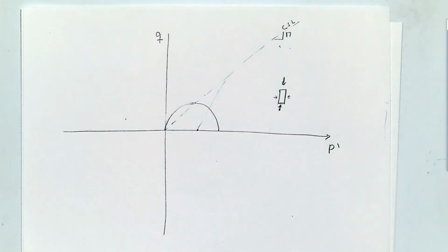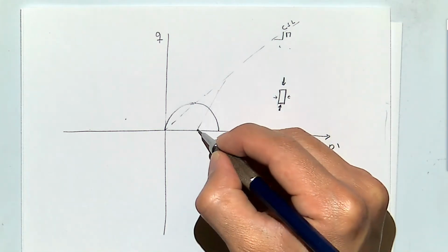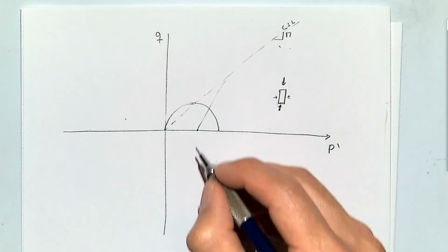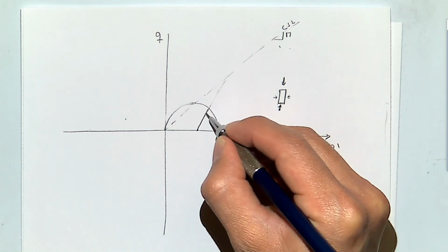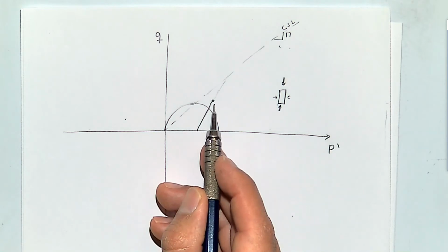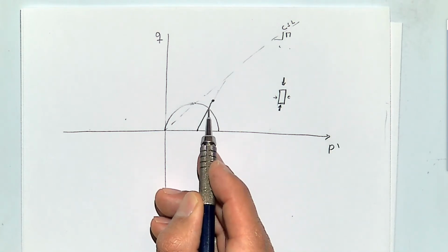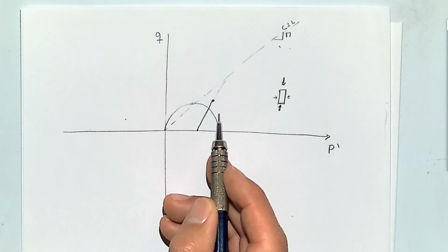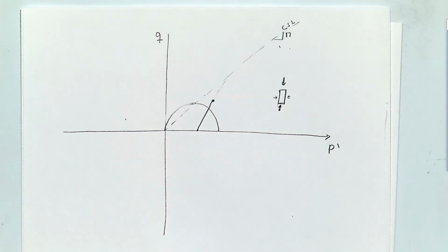The result of this triaxial compression is that when you go over this yield line, and let's say somewhere you stop over there, you have compacted the material and you have gone through a plastic strain after you cross that line. Because you go through a plastic strain, the porosity of the material now is lower and it's irreversible. And that loss of porosity is going to make that mud rock stronger.